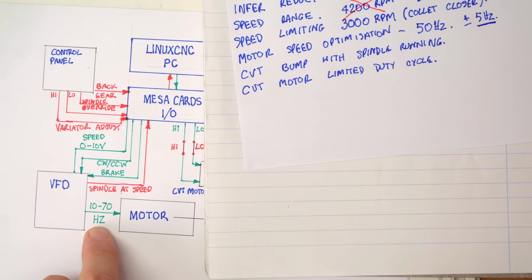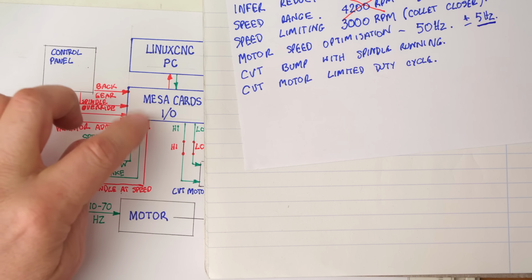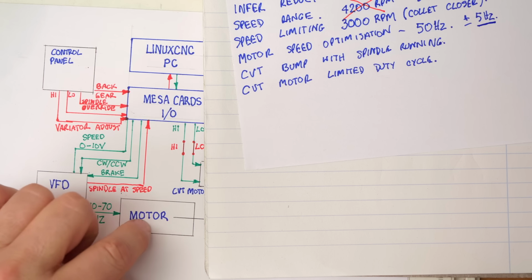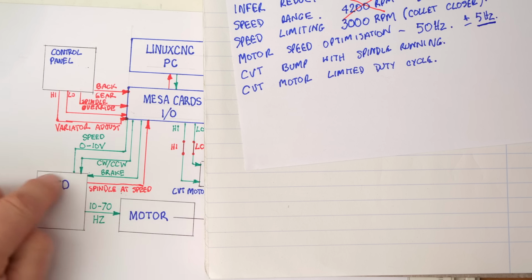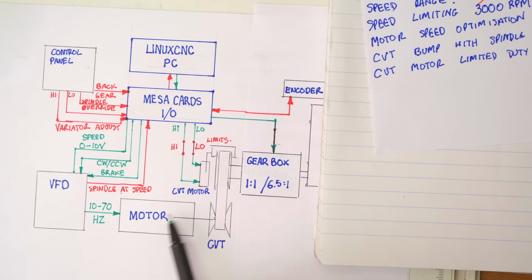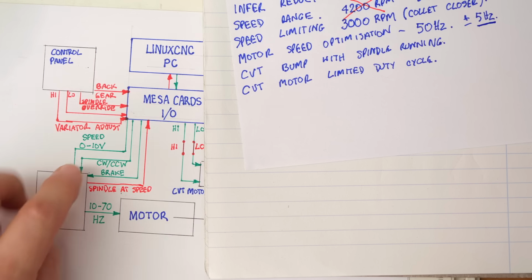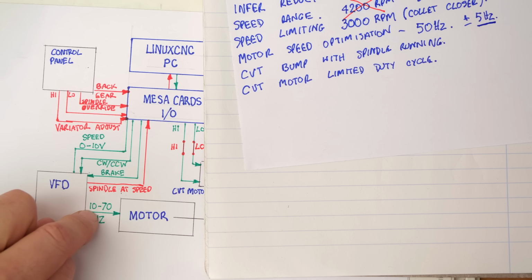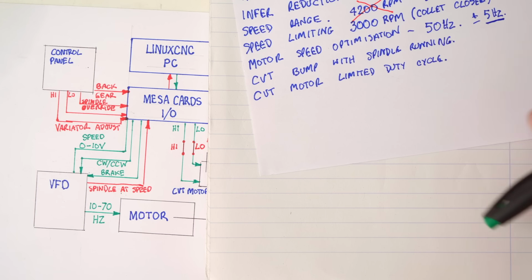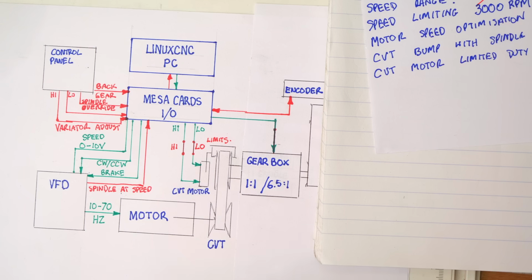However, the problem here is that this value is not actually motor speed, it's what we're commanding. So on the one hand, we'd be trying to control off a variable that we're constantly changing, and that's probably going to lead us to some pretty major dynamic issues and limits in this whole system. For example, if the motor's running at 10 Hz and we command 70 Hz, that command signal will instantly go to 70 or its equivalent motor RPM, while the spindle's only just started accelerating.